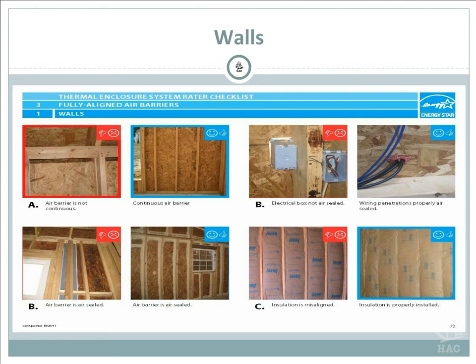Again, the insulation on the left, you can see how it's back in there. It's not even with the 2x4s. It's smashed back in there. The one on the right is done correctly. It should be an even flow. You want to remember that word, continuous. It's a continuous level of insulation, a continuous run, and it sits there all the way properly. You don't even see the 2x4s. All you see is the paper. Again, these are examples of what we talked about just a little bit ago.